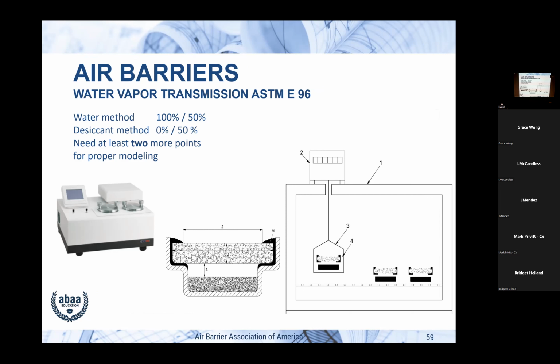This is one that you really have to be careful, because if you sort of look at it in a very simple way, we're talking about how water goes through material at 23 degrees C and at either 25 or 75% relative humidity. How many times, and the code says you got to do the desiccant, so that's at 25% relative humidity. Think of your wall cavity, think of your atmospheres you have here, your weather. How many seconds in a year is it going to be that exact atmosphere? And I did say seconds, okay?